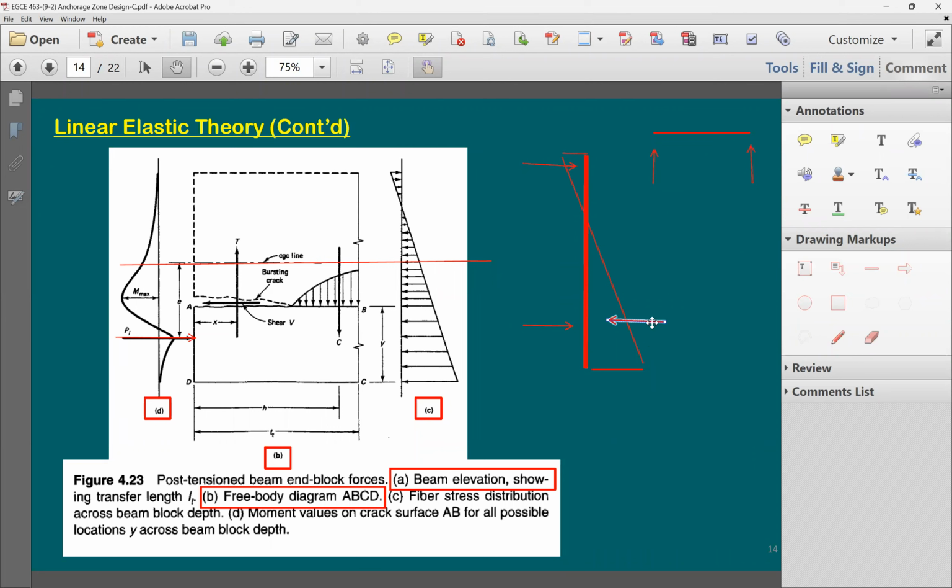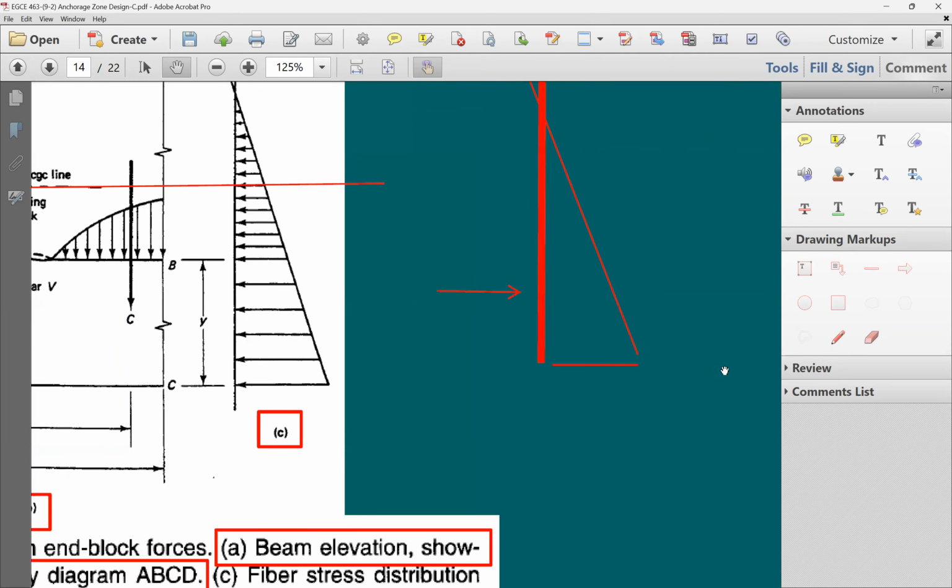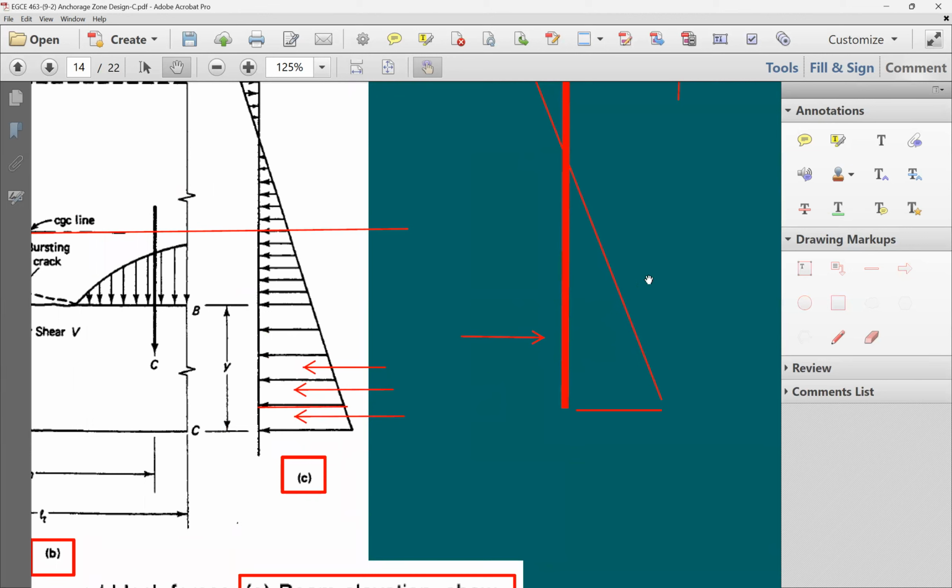So what you need to do, if you'd like to do some analysis, is to split this stress distribution into very small segments. You see, here's one segment, right? This is going to be my segment. And for that, you're going to have a force here. You can do integration only for this section, so now I'm going to have a force coming in this direction. Do the same thing for this segment, another force here, and the same thing, another force here. You just continue. You're going to fill it with lots of forces. So instead of having a stress distribution, I'm going to have a bunch of forces.